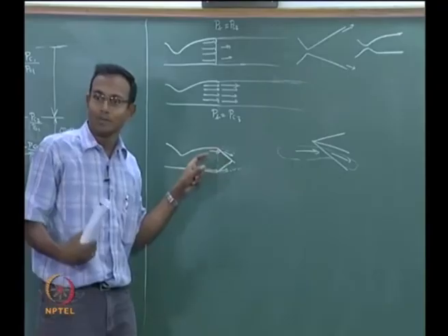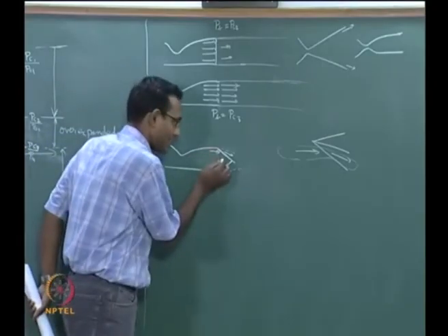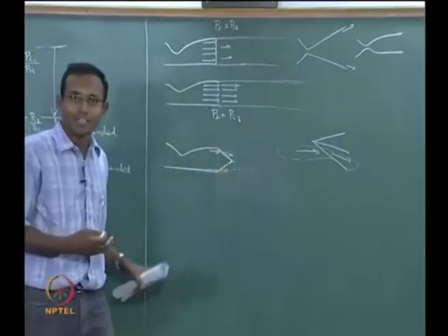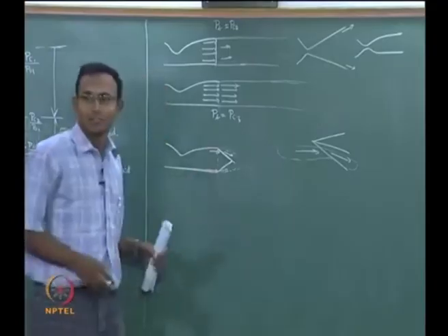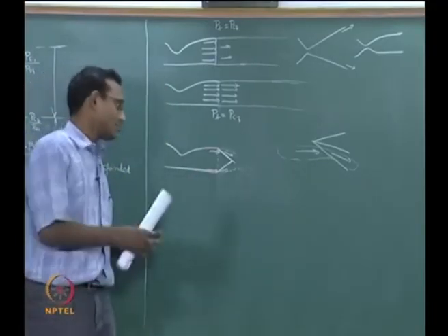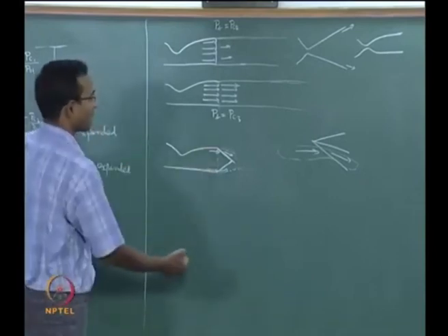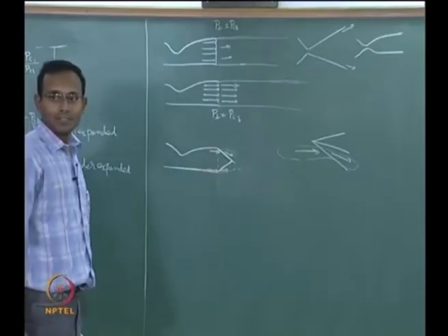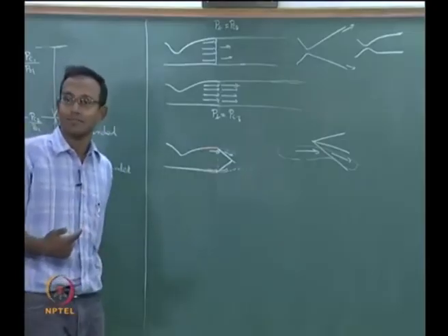Oblique shock cannot be a 1D problem, it is a 2D problem. So now I am going to talk about inside here one Mach number, above the shock there is another Mach number. That is the best I can do now, okay. It is already 2 components at every section I think about. So the idea of this is this. Now I say I increase my back pressure a little more, what happens? The shocks have to be a little more strong, okay.